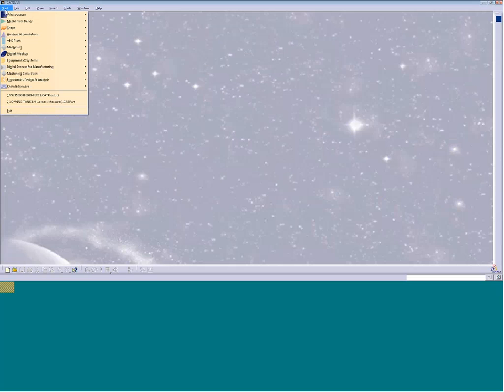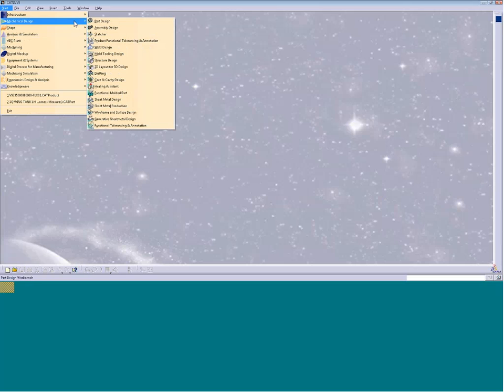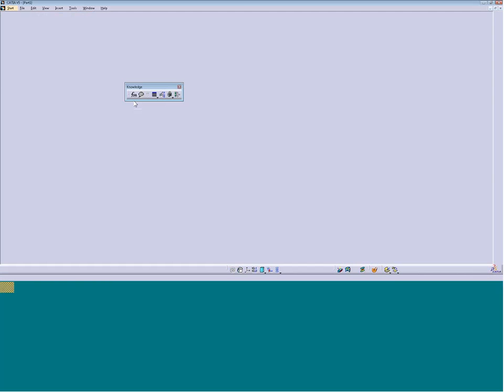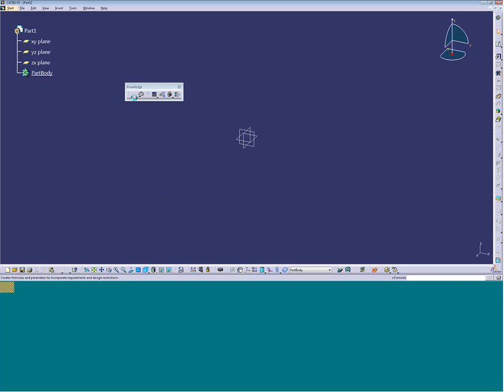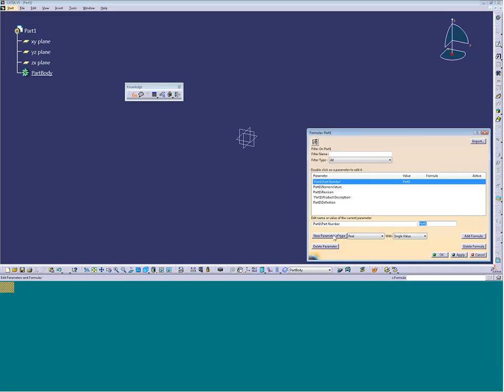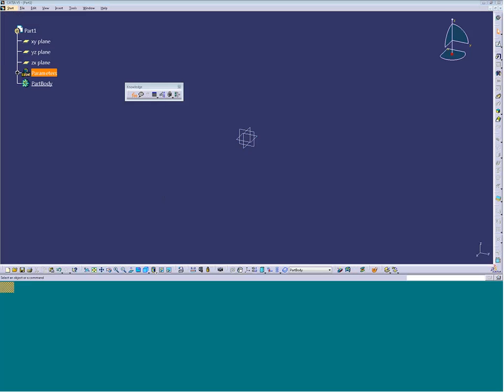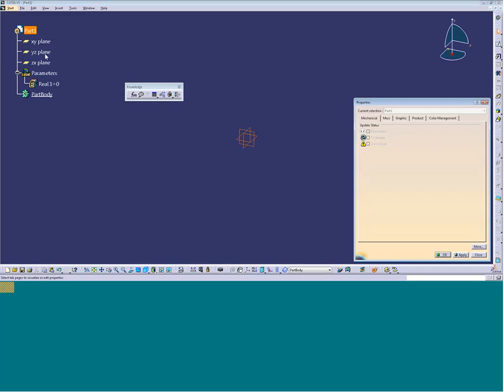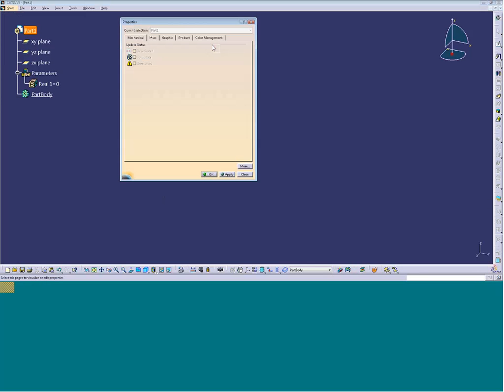And one of the issues that they ran across at Parker ESD was that in some cases they had parts that were legacy parts. As many of you know, you can create parameters using user parameters here, which would show up in the tree. So if I created one of type real here as an example, it would show up at this location. However, there's other parameters that show up under product properties, which were equally important for the drawing purposes. And when we come in here and take a look at the product properties, part number, revision, nomenclature, some of these Parker ESD was using.